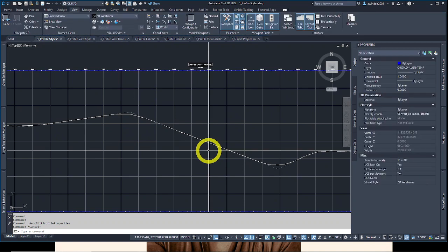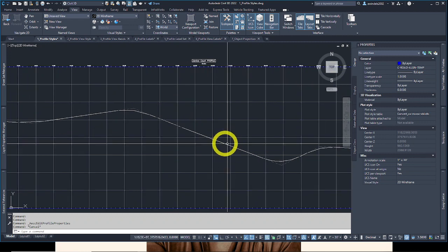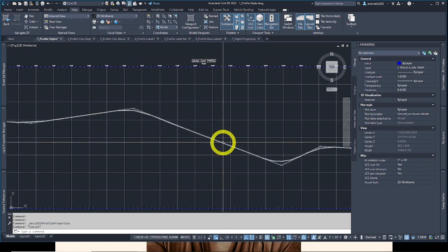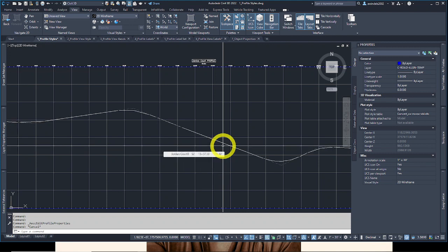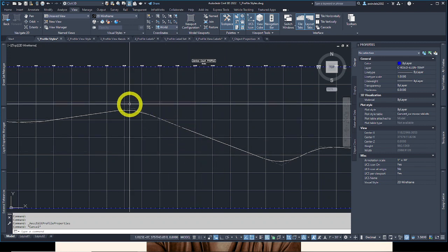So using styles like this has an advantage. A lot of times it's nice to have a Civil 3D style that turns something off temporarily. It has advantages over turning layers on and off. First, many Civil 3D objects have multiple components that can be displayed on different layers. So they're like onions. They have layers within them. So you can't just turn off one layer and turn off what you need. There could be 5 or 6 layers that make up a Civil 3D object.